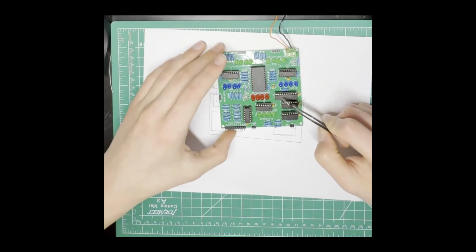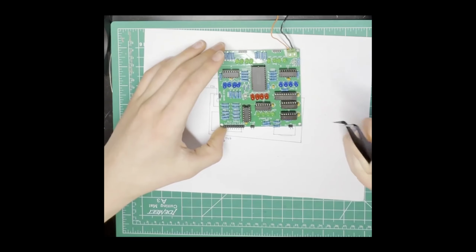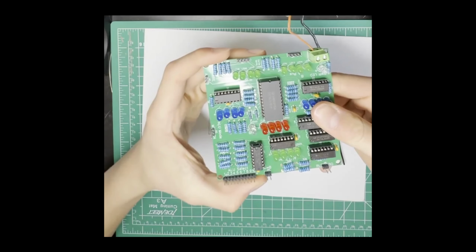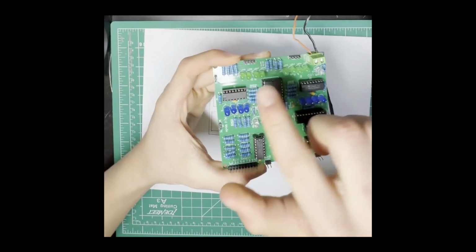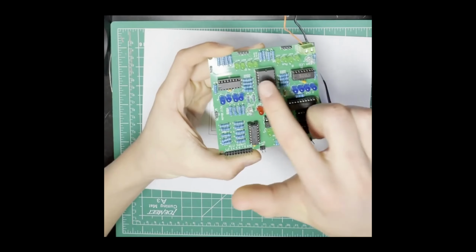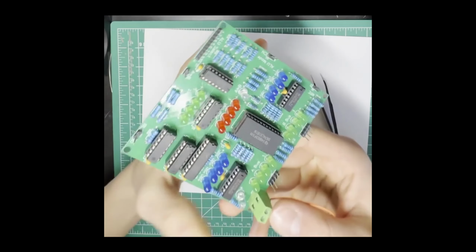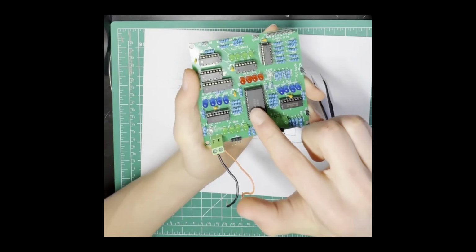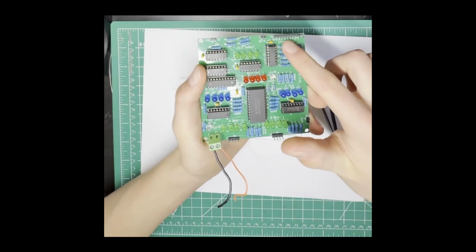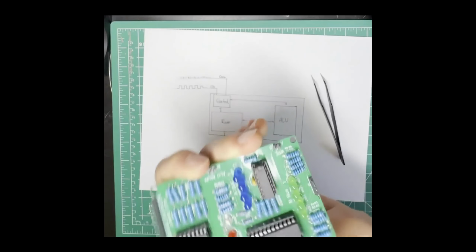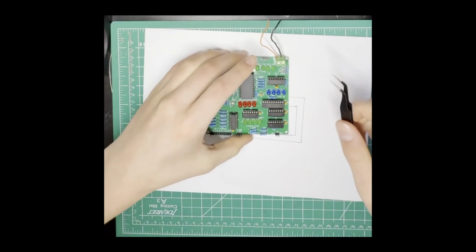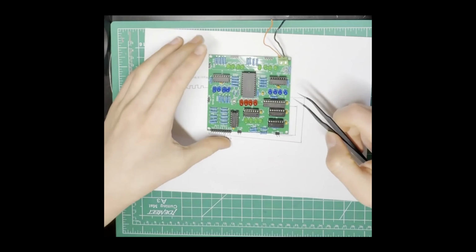Once that, you can also output this onto just the output bus in general. And then we have a couple more inputs. We also have our A and our B input. We have our write enable to write to these registers or RAMs. And then we have our ALU select line, which has basically a demultiplexer inside this ALU, which chooses which operation you're doing. And this matches up to the demultiplexer that controls this whole thing.